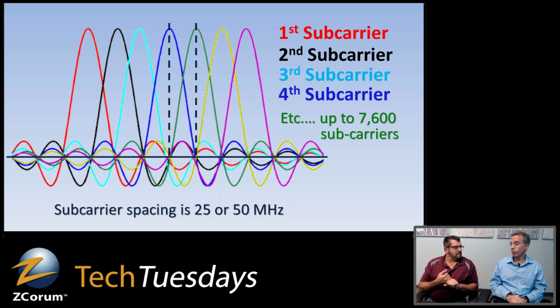Well, no, that brings up a good point, because what he's talking about is, on DOCSIS 3.0 and lower, if you had a customer or an area of your plant where you could only do QAM 64, then basically for everybody there you had to do QAM 64. Yeah, if you don't have enough quality space to run signal, whatever QAM modulation is on that frequency, that's just what it is. It is what it is. It's your lowest common denominator that you have to do.